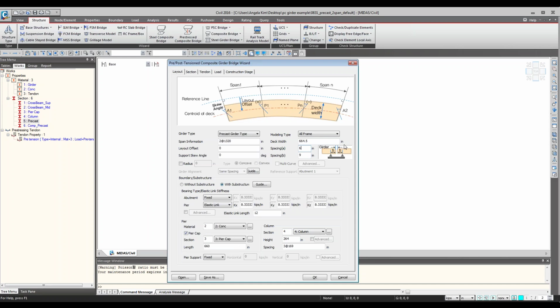This also means that before the concrete pouring, the dead load is at the non-composite, non-continuous state. So when you extract your non-composite dead load result, the results are based on the non-continuous, simple span condition. After the pouring, this gap will be filled so that the bridge is continuous in case it's a multiple span project. So that's what spacing A and B are for.